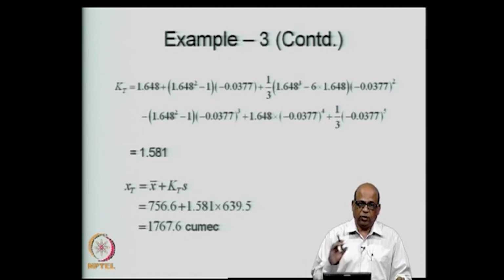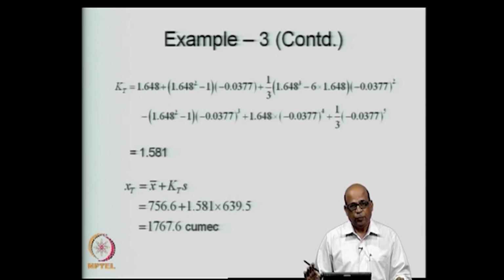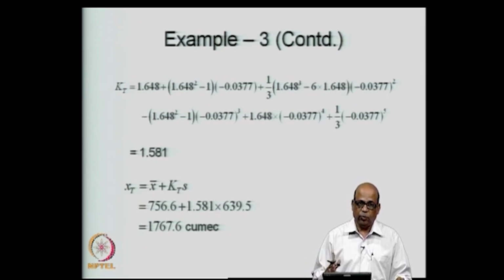Also the correct data series, whether you use the complete data series or the partial duration series or the annual exceedance series or the extreme value series, and which among several of these extreme value distributions that we talked about you use. So, there is also a judgment involved, and also analytically or otherwise you must be able to judge which distribution best fits the particular data that you have.